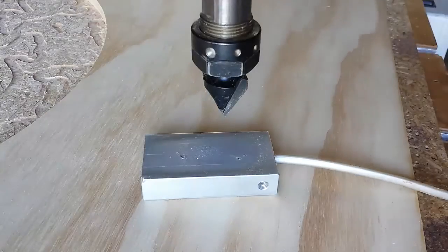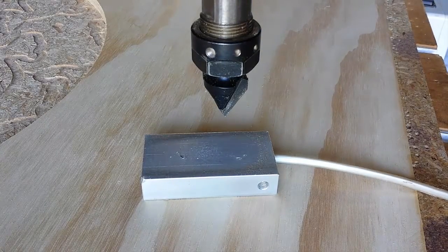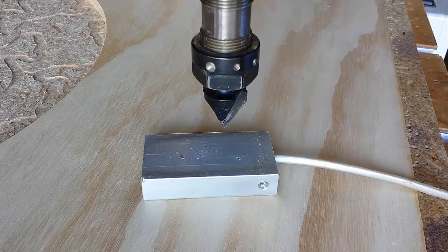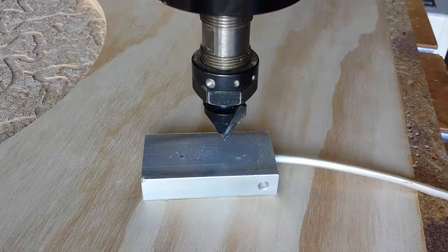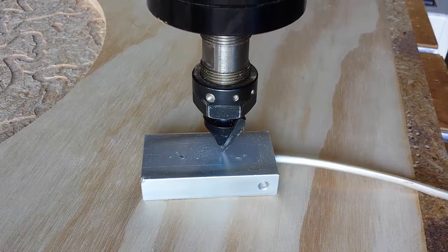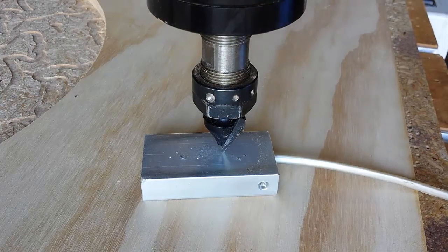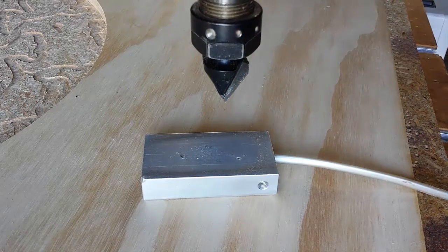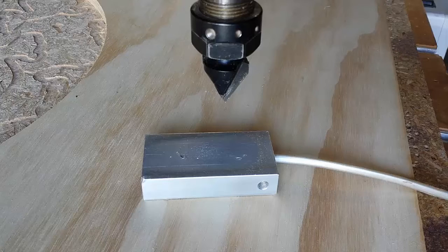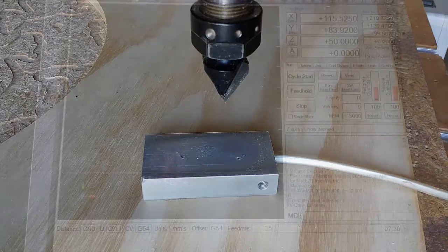To set the vertical or Z axis, we use a special 16 mm block designed for the purpose. A special function in the software slowly lowers the head to detect the 0 position for the Z axis. The Mach 3 software is programmed to allow for the 16 mm block, so in effect the 0 Z axis is now set precisely to the surface of the plywood.